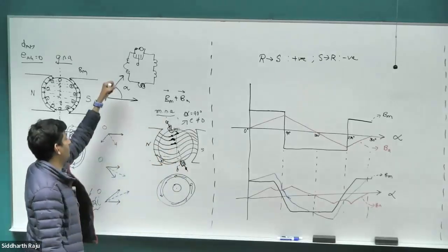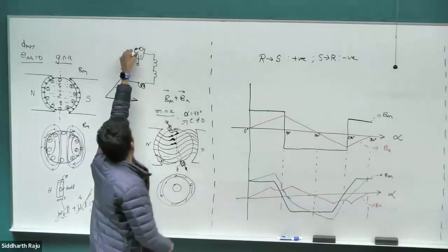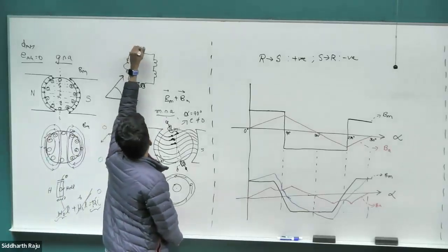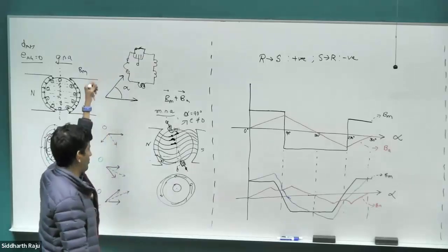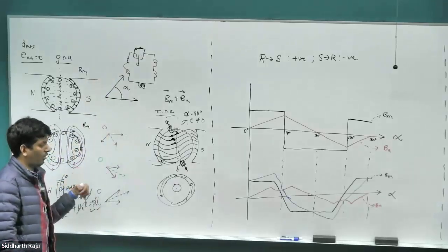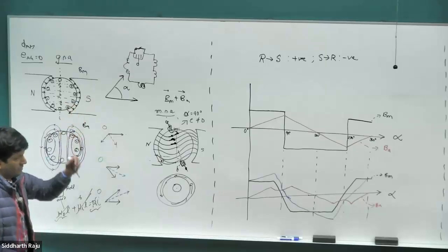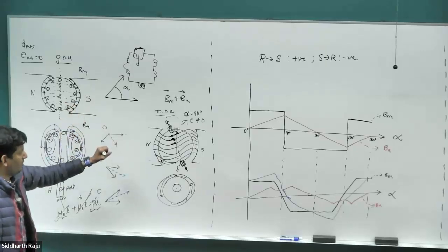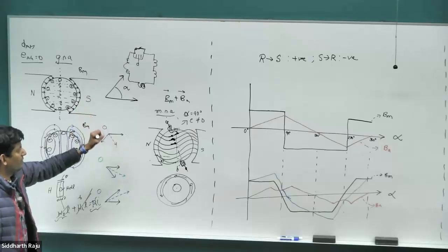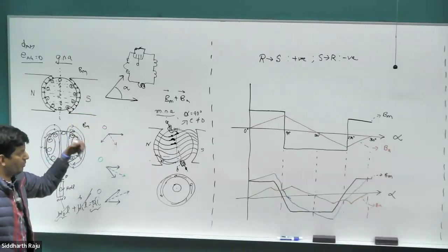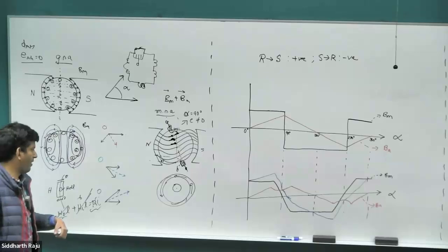Then the EMF will be 0 at this point, and then we are no longer shorting a voltage source across an inductor. So there's nothing charging up the inductor. At least the current would not be as worse as it was before. There is still the part where the current in the inductor is delayed. That is not addressed by this shifting of the brushes, but at least we can address the fact that there is no additional EMF contributing to the current being delayed further, right?